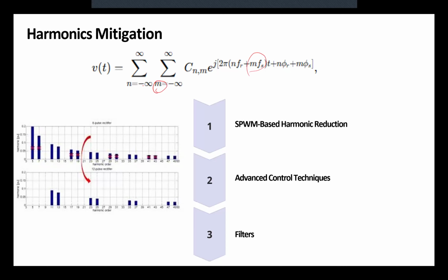So we already have 5 factors that you could see affect the Fourier series that we could control in our SPWM strategy. So basically, you could run an optimization code in MATLAB to find out what configuration of these 5 parameters will give you the best possible output.